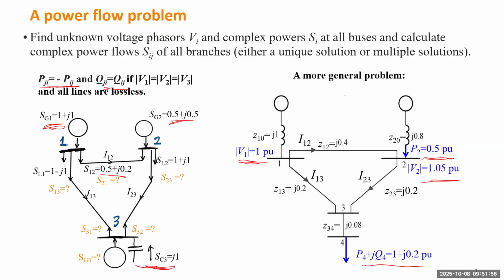So I have an exciter or automatic voltage controller, and I can set the setpoint for the voltage. So 1.05 means this generator's terminal voltage will be slightly higher than the base value, about 5% higher. So this can make the generator produce some reactive power for the neighboring buses.